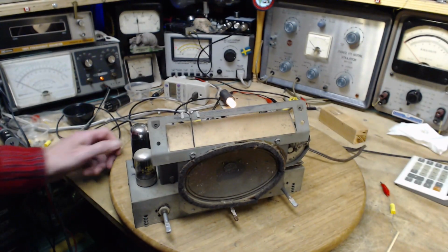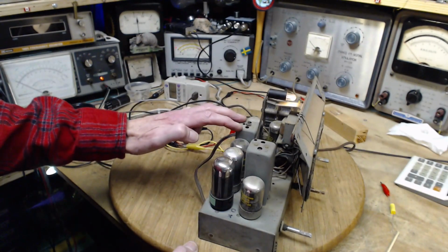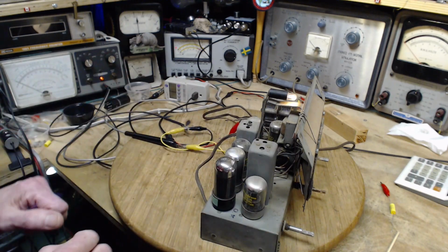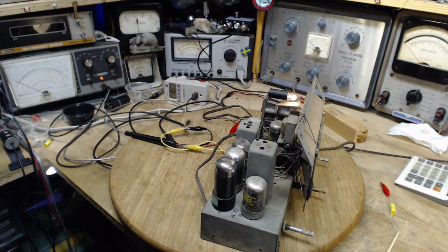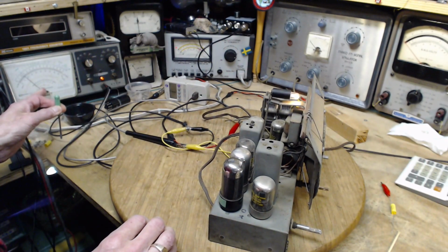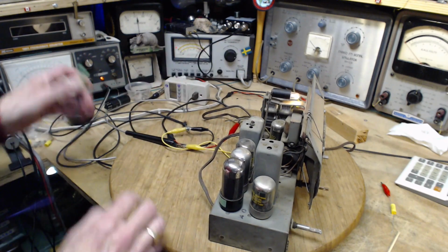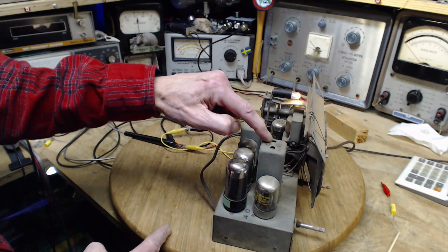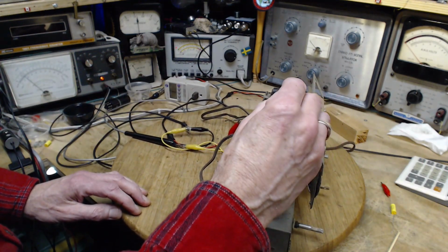So the assumption is these two transformers, one of them's tuned to 455, the other one's tuned to around 400. Something like that has happened. We're going to try to figure out which one is tuned where, so I'm going to put the signal generator at 400 here. If I adjust the 400 one, we'll see a big change on the meter. If I adjust the 455 one, we won't see much change. That's how I'll identify. I notice the screws are down low in here, and they're right up near the top on here. So we're going to start with this one.